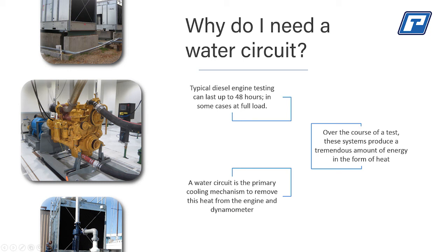Number one, when you're testing a diesel engine, that's typically the use for a water brake dyno or for any dynamometer in our field. You can be testing this engine for anywhere from 1 hour up to 48 hours and sometimes longer for marine engines. So you've got to have a method of removing the heat from the engine and the dyno, cooling the water back down, and reusing it and recycling it. So by far that's the biggest issue with that.